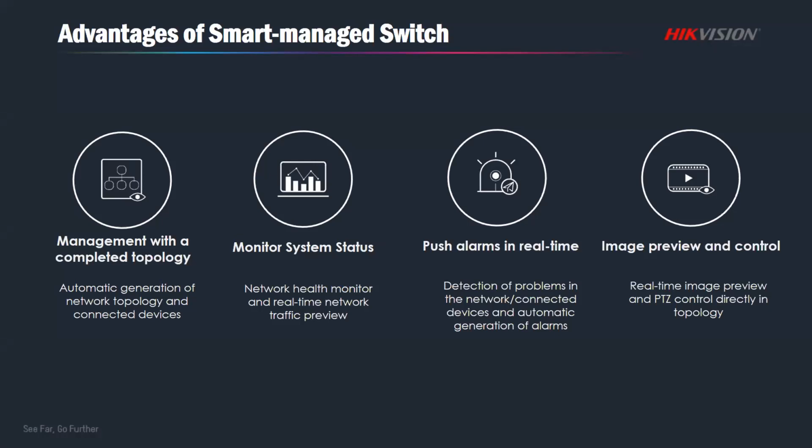Consider monitoring the system status, as it gives you live active monitoring of your network. If you do have any fault issues or anything like that, you'll get push alarms in real time. That can be, as I mentioned, a push alarm or via an email. And of course, it gives you live preview of control. So from a remote position, from a switch, you can dial into a system, have a camera for instance, see that it's there, it's functioning, the image is what you expect it to be. So it gives you a lot of power remotely before having to attend the site.